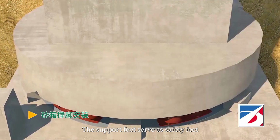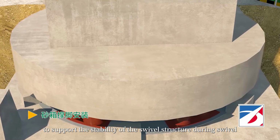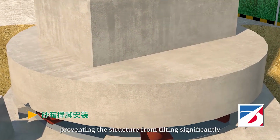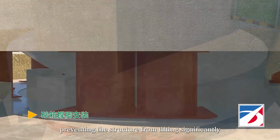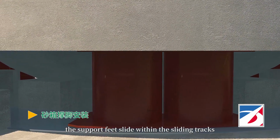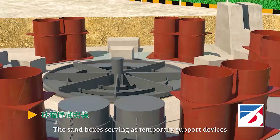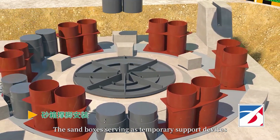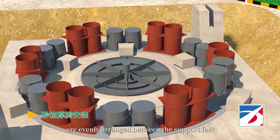The support feet serve as safety feet to support the stability of the swivel construction during swivel, preventing the structure from tilting significantly. During swivel, the support feet slide within the sliding tracks. The sandboxes, serving as temporary support devices, are evenly arranged between the support feet.